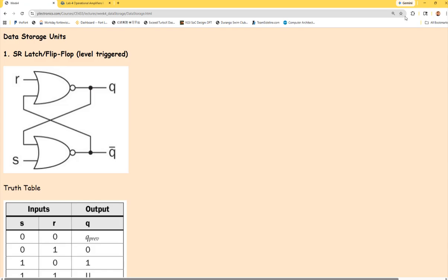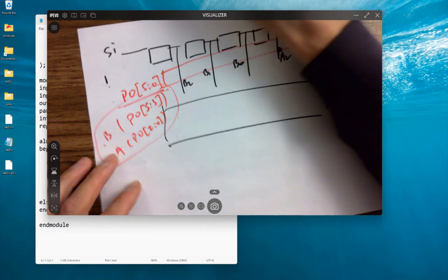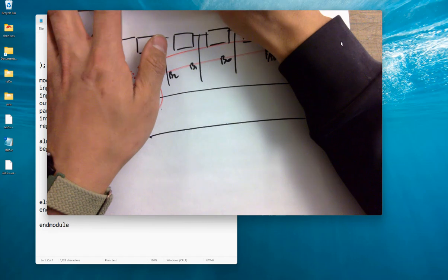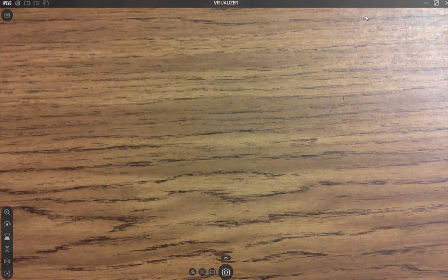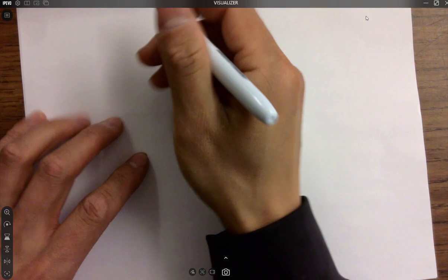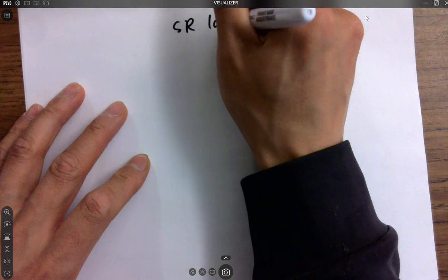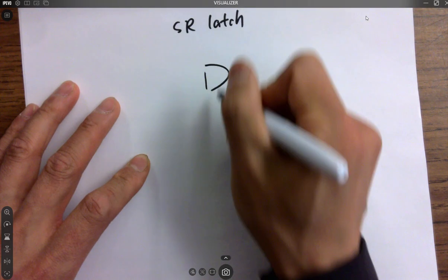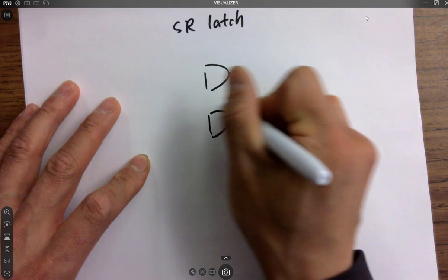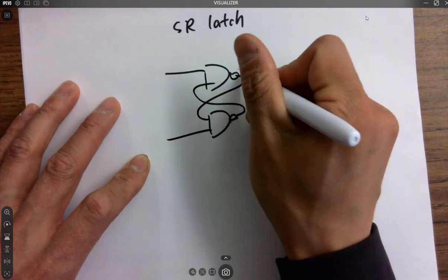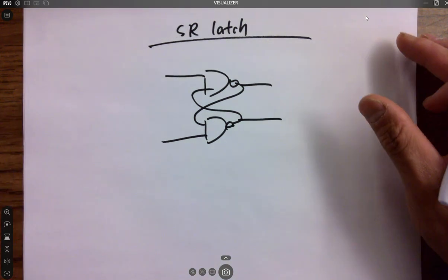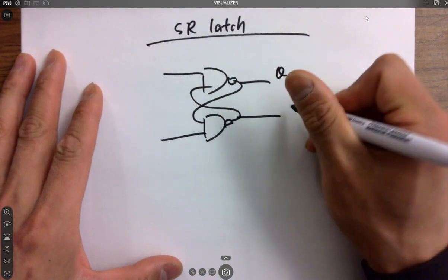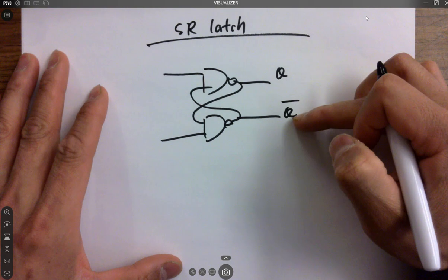I think it's still good to remind you guys of the things over here. The SR latch has 2 different structures. You can use NAND gates to form SR latches, or you can use NOR gates. My question for you guys is, since some of you already took VLSI, which is S and which is R, when we define this as Q and this as Q naught?